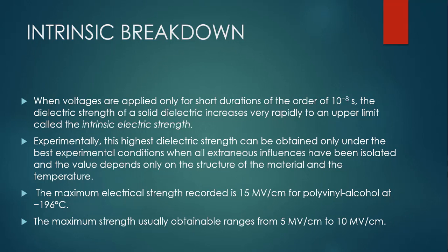So intrinsic breakdown is basically a theoretical one. You do not get it in the practical sense because you cannot remove the other influences. So it is only when the short voltage is applied. This is the maximum insulation property that a solid can show, that is the intrinsic breakdown.